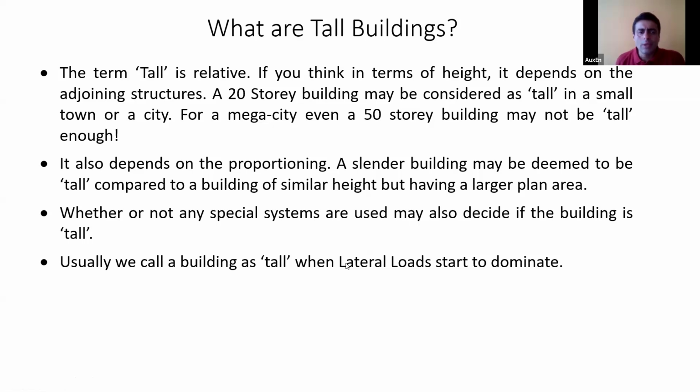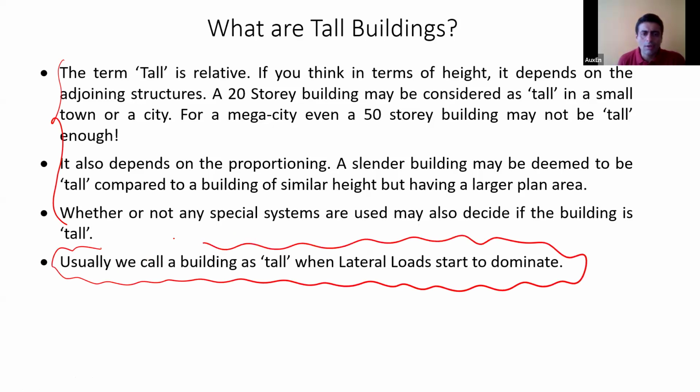But usually neither of these three or four definitions are used as such. The parameter on which we generally like to call a building tall is when lateral loads begin to dominate. So if your lateral loads like seismic or wind begin to dominate the serviceability design and the strength design of your building, then usually we like to call our building tall.